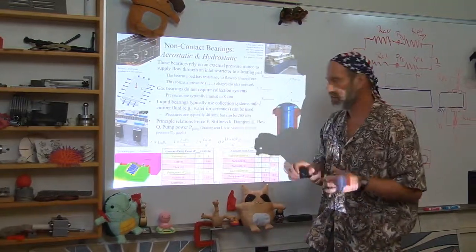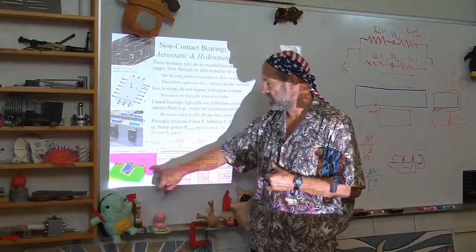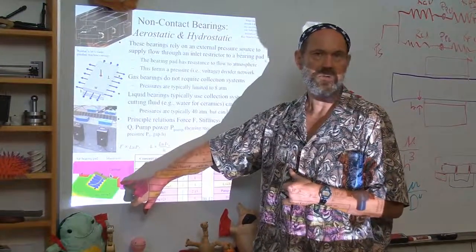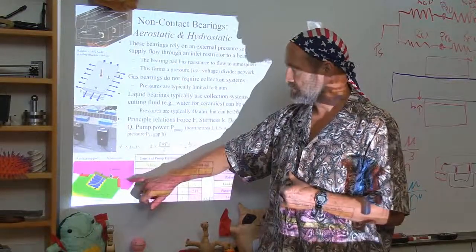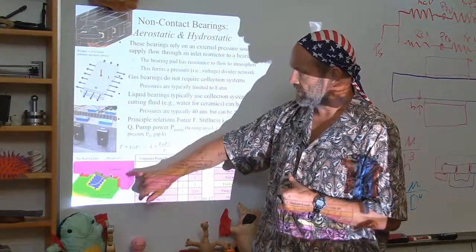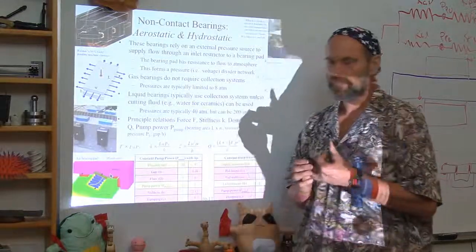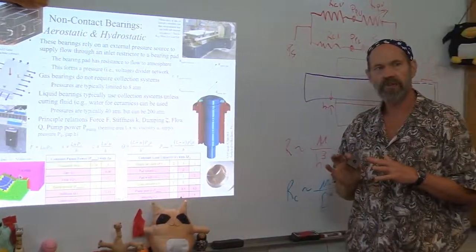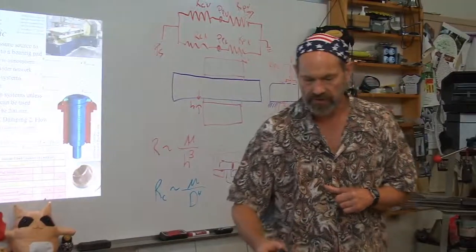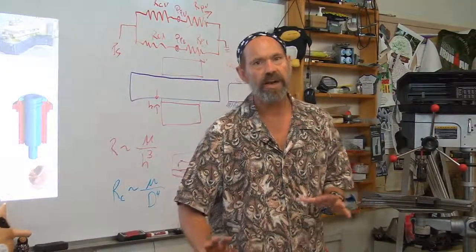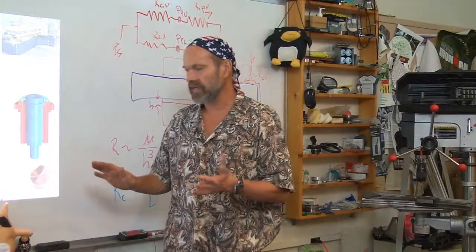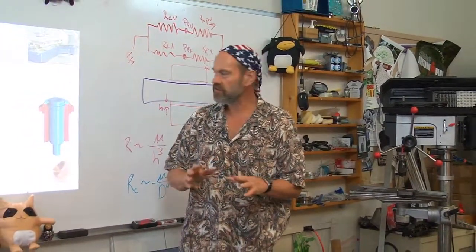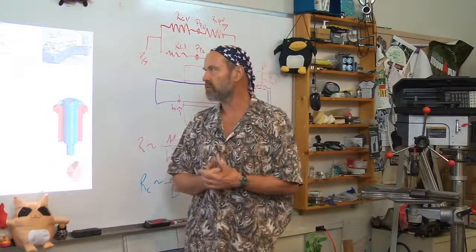Or for very, very precise systems, you can then pump epoxy behind them and fix them in place permanently until you break the epoxy, without having to precision machine your carriage. So some very interesting novel ways have been discovered for making very, very high precision machines using very, very simple structural elements, air bearings. You can also use this method with hydrostatic bearings.